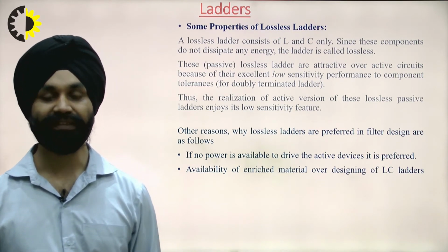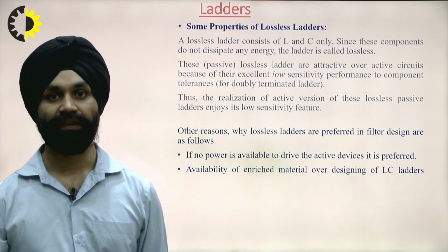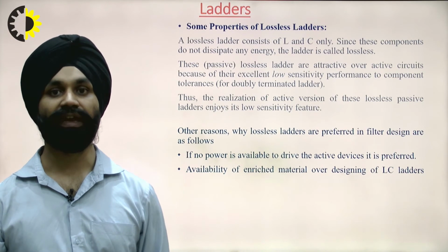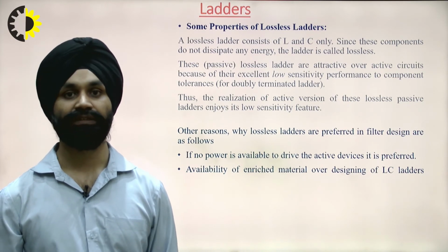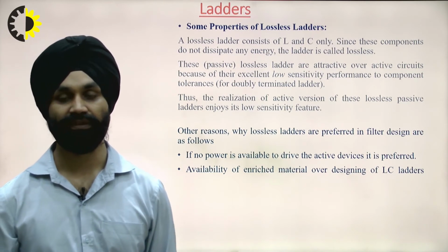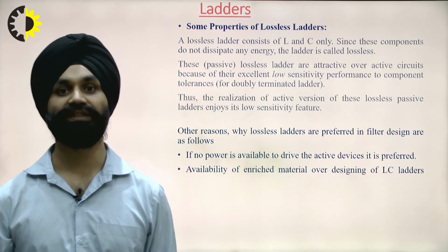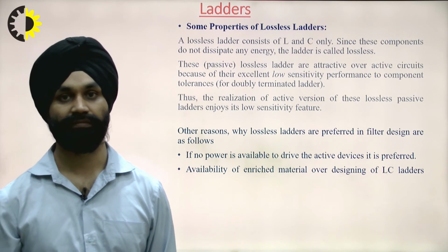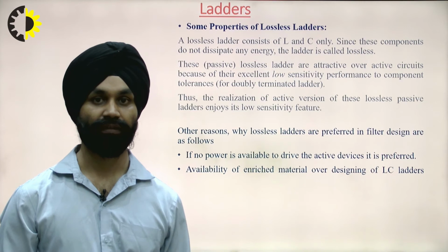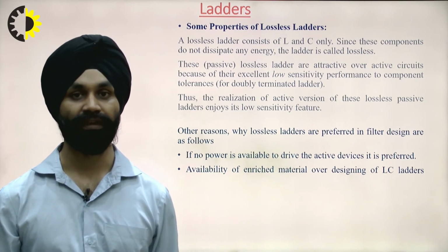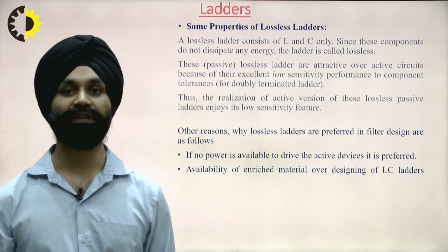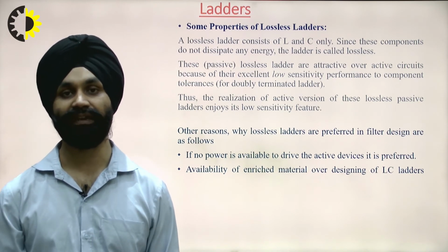This makes possible the realization of the active version of the lossless inductors using passive filters, which have low sensitivity features. So we can use components of L using GICs, which gives a combination of both passive as well as active circuits.